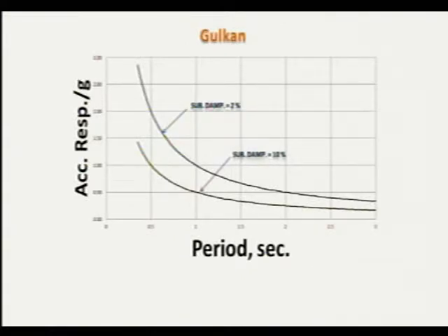Then, forgive me for using jargon, but if we take a broadband earthquake, one that has high velocity from about 0.5 seconds in the response spectrum to about 2 or even 3 seconds, then what happened was exactly this.